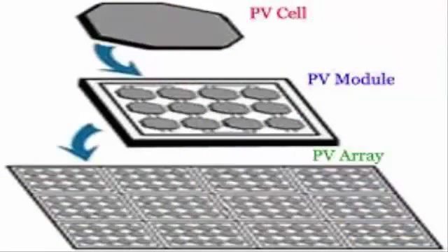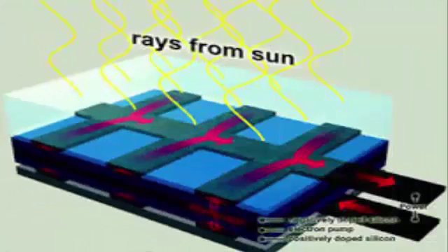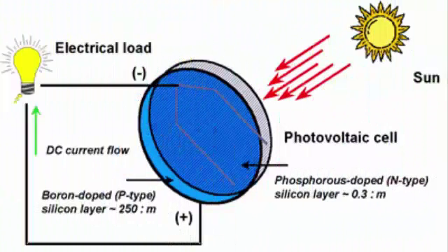Photovoltaic cells. Light is incident on a p-n junction, essentially a photodiode, and electron-hole pairs are produced, giving a small potential difference across the junction. The phototransistor is simply a junction transistor in which the light is able to fall on the base region, producing electron-hole pairs. Photoconductive cells are those in which the resistance of the cell changes due to light. One very common type of photoconductive cell is the light-dependent resistor, LDR.